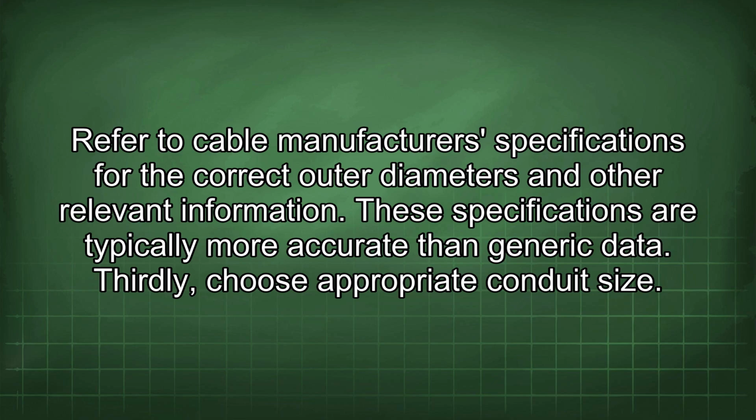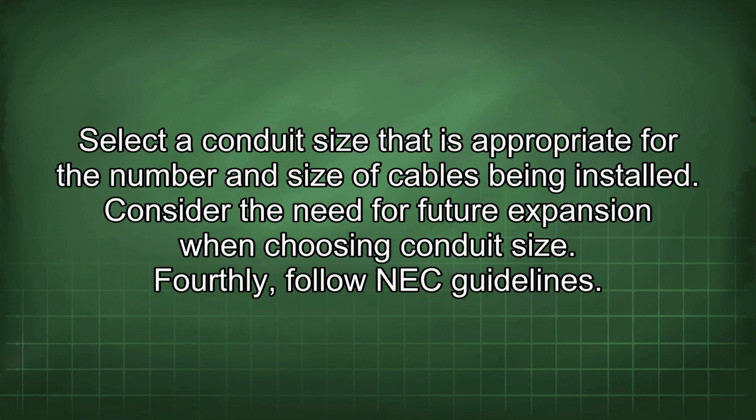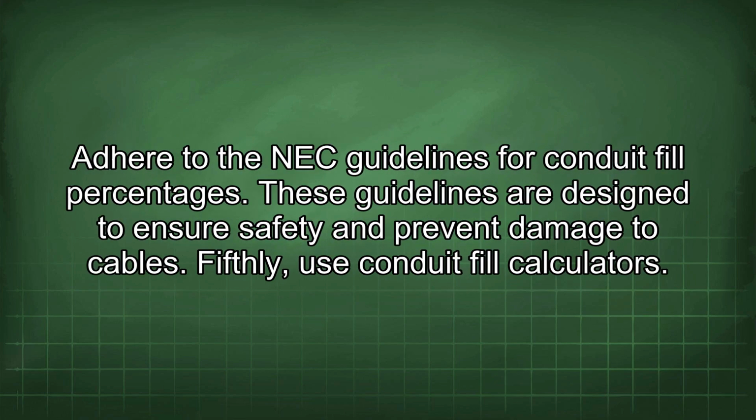Thirdly, choose appropriate conduit size. Select a conduit size that is appropriate for the number and size of cables being installed. Consider the need for future expansion when choosing conduit size. Fourthly, follow NEC guidelines. Adhere to the NEC guidelines for conduit fill percentages. These guidelines are designed to ensure safety and prevent damage to cables.